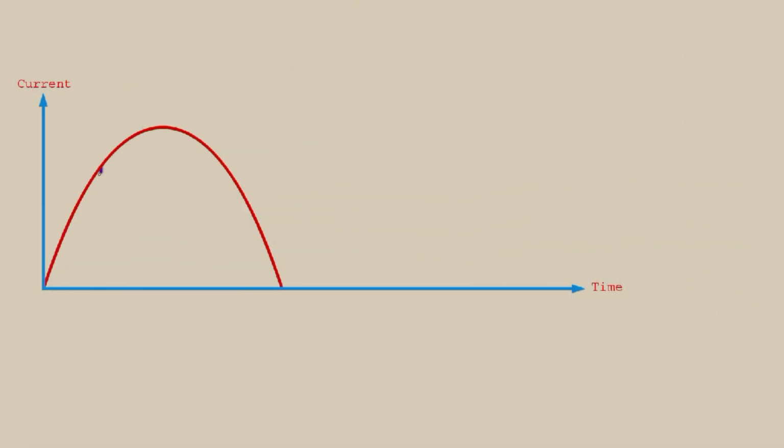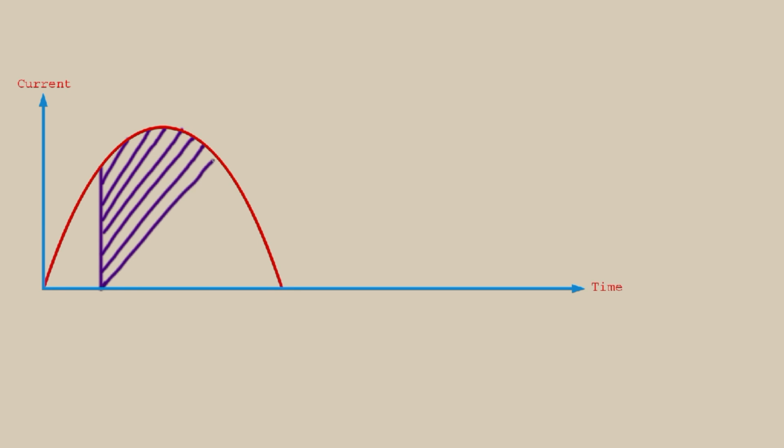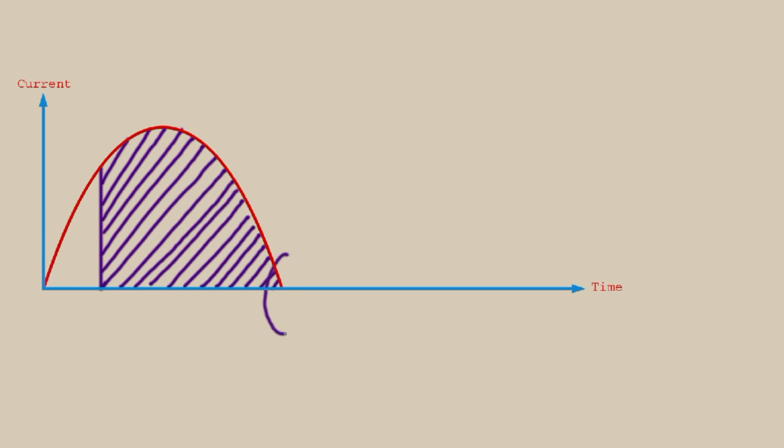Say, at this instant, the moving contact gets completely separated from the fixed contact. The current still continues due to the metal vapor arc. This is the first zero crossing. Here, the current becomes zero, causing the metal vapor to cool and condense. For the next half cycle, there will be no metal vapor left to sustain the arc as it has already condensed. However, practically, due to restriking voltage, the arcing may continue for 1 or 2 more cycles.